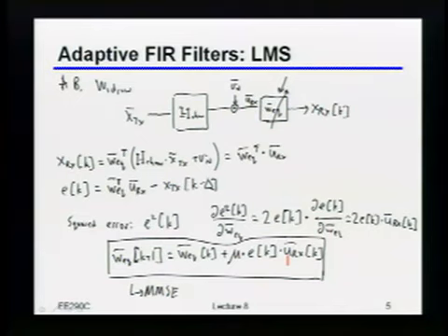But in that case, XRX should still be a vector, right? No, remember, because I'm doing this as a function of k, when I move to the next k, that will still just be a single sample. So in other words, I'm taking the instantaneous error at this time, and I'm correlating it against all of the inputs that either are now or previously into the equalizer.